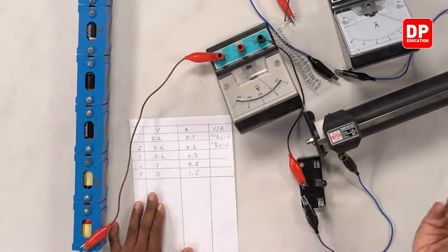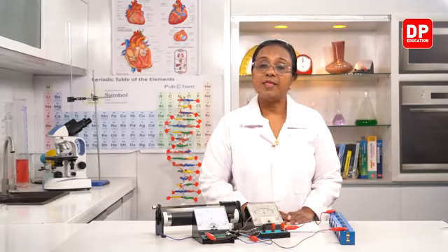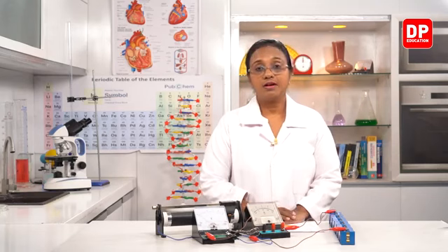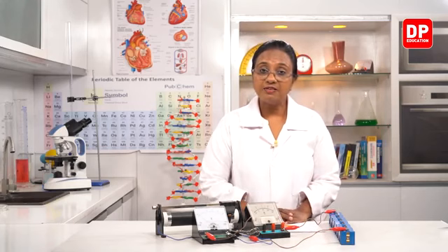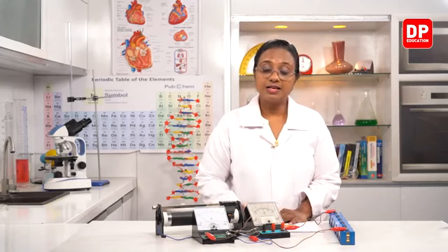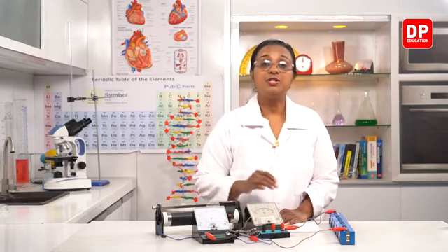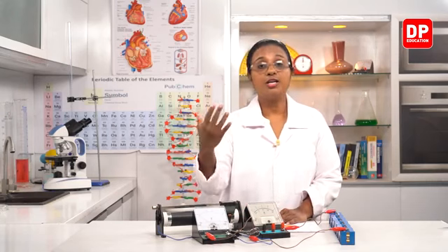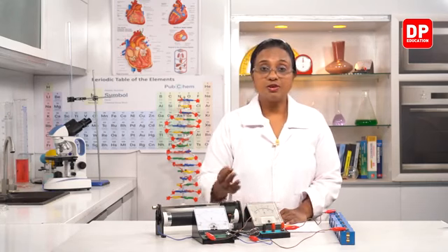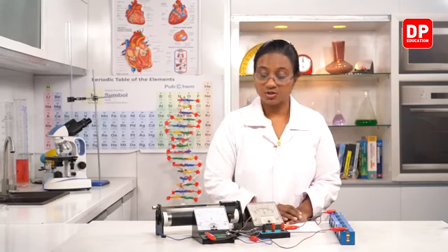And that is what we will be calling resistance, and from that we will come to the point where we discuss Ohm's law. So I am sure, students, you all understood the activity, how we connected the circuit, and why we need to maintain the temperature. The temperature of the nichrome coil should not increase, because then the resistance will change, and because of that the current flow will change.